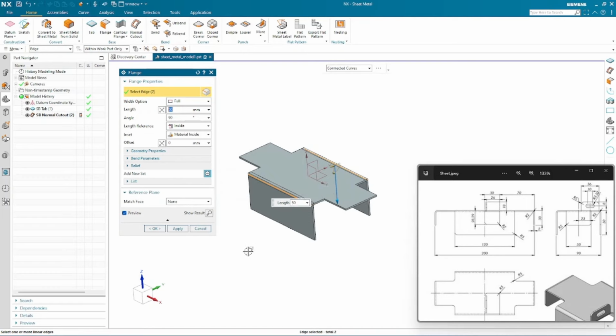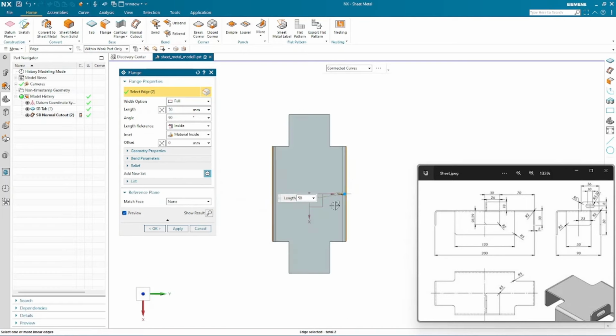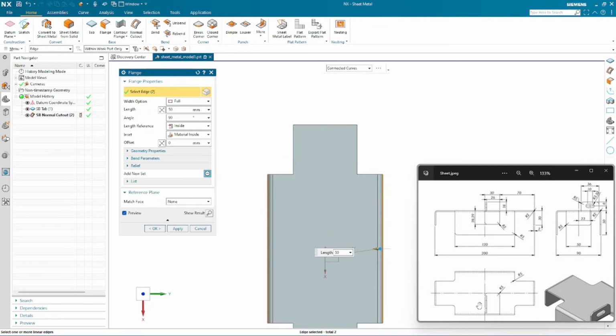Now another thing I would like to share here, as you noticed that we created our first tab with these dimensions, 290. Now thing to notice is here 200 is from outer edges of the wall including the thickness. Same here with 90, it is including our thickness, the total width of the part.